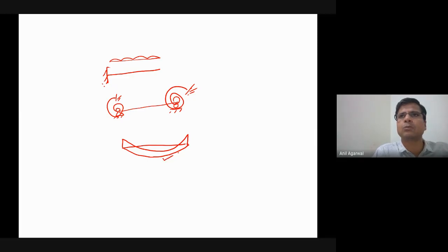But the bending moment diagram for a beam with some springs would be somewhat like this. One thing you should notice is that the bending moment diagram shape does not change. And that factor 1.5 was basically driven by the shape. Because if the shape is this kind and maximum bending moment is here, then again a large part of the beam would be under a very significantly high bending moment. Same as in this case. And in this case, anyway, that logic still holds true.